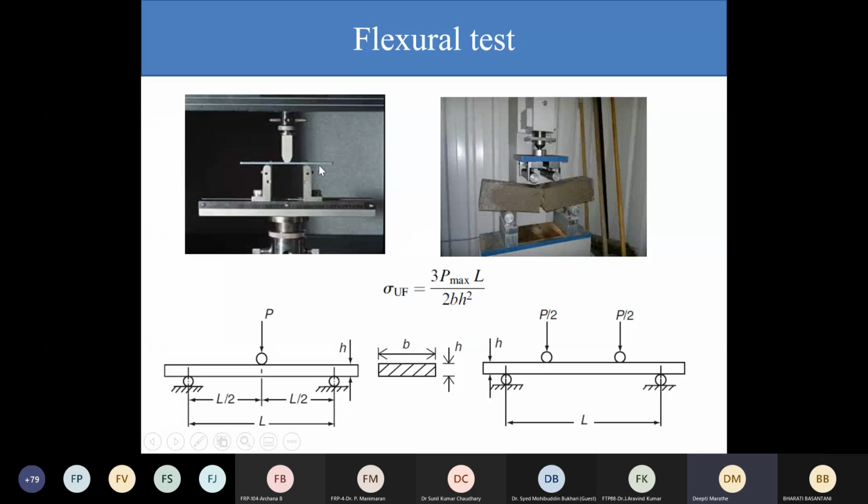Now the specimen preparation, that is the length, the width and the thickness of the specimen, is as per ASTM standard D790. But in this case, what is important is the span length, and that is determined by the thickness of the specimen. Now these flexural tests, 3-point or 4-point bending, their values are nowhere going to be used for characterization of the lamina, but this is going to be a quality assurance test or a screening test. So for that, I'm going to do the flexural test.